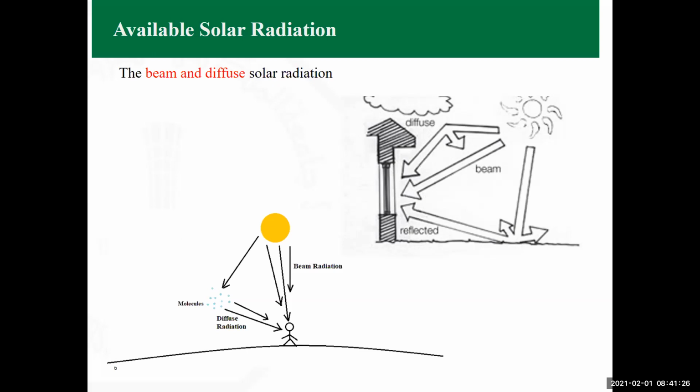A photovoltaic panel, when you are talking about efficiency, is the ratio between the amount of energy that you get in the form of electrical energy divided by the incident energy falling onto the solar panel, which means that if the solar panel is receiving 1000 watt per meter square, for example, then what you get is going to be 200 or 240. If it is receiving 400 only because there's a cloud which is partially covering the sky and it is receiving less radiation, then what you are getting is something between 80 and 90 watts.